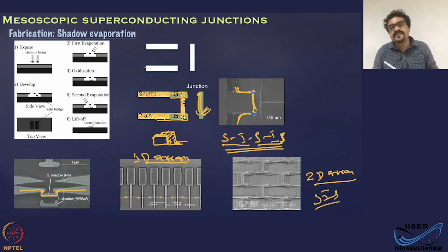That's what it is. Again, the only thing is you need to cleverly design the pattern and cleverly choose the angle of tilting when you metallize it. So here we have junctions at every point. It's a two-dimensional array of junctions. All you need is to tilt between two angles, and you need an oxidation step in the middle.